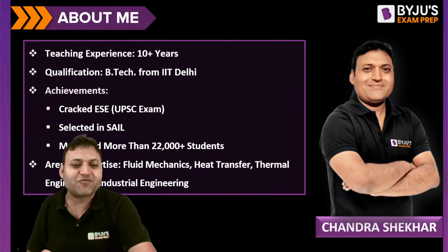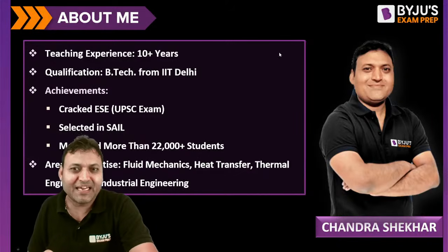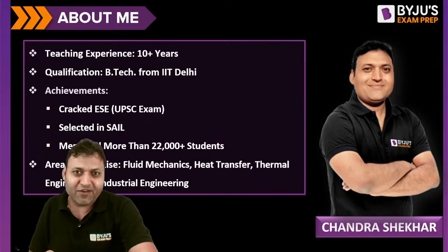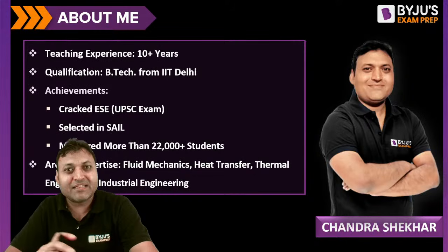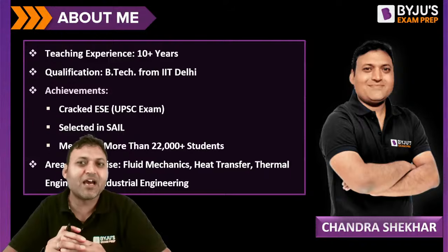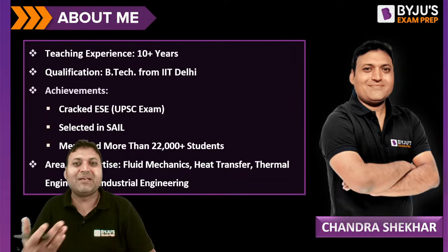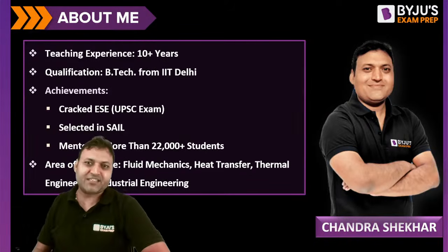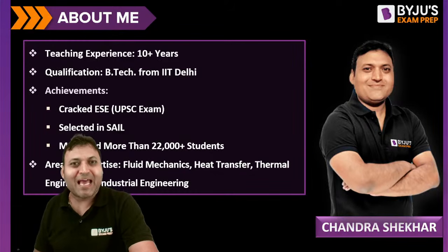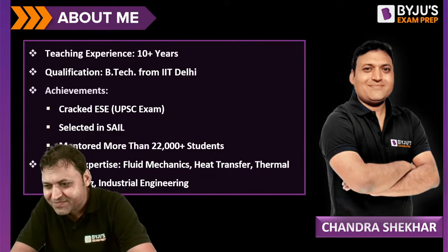And NTU stands for number of transfer units. It gives the information about the size of the heat exchanger or area of the heat exchanger. Even though NTU is unitless, the magnitude of NTU stands for the area of the heat exchanger. So the lesser the size, the lesser the area, the more will be the economic performance of the heat exchanger. So LMTD should be as large as possible for a better heat exchanger, and NTU should be as small as possible for better economic performance of the heat exchanger.